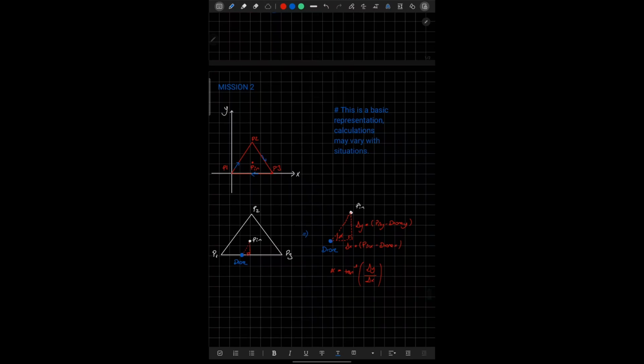For mission 2, the steps are pretty much the same as the first mission. First, find the positions of each vertex and the center point in the net. Then we can create a list of waypoints that will form the edges of the triangle. After that, with simple trigonometry, heading could be computed for each position. By looping through the lists, the second mission could also be accomplished.